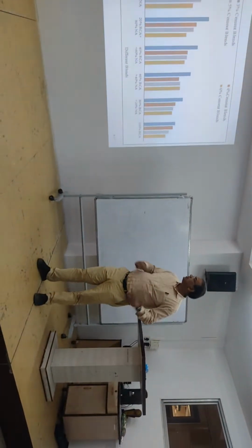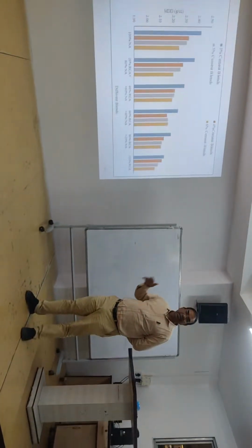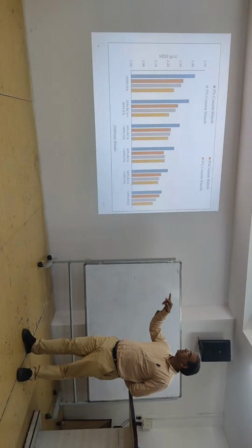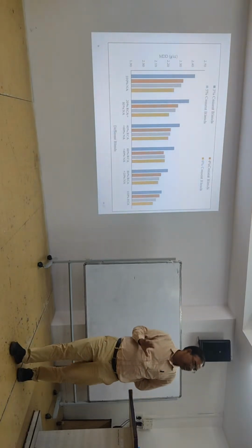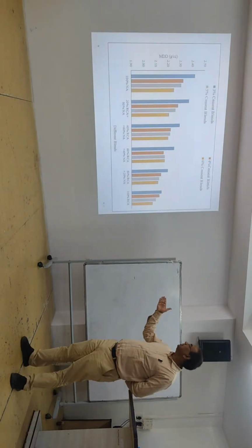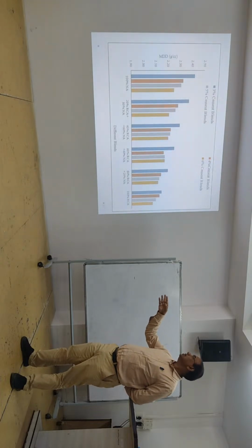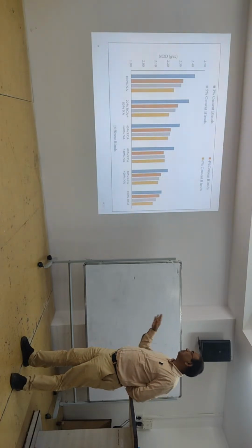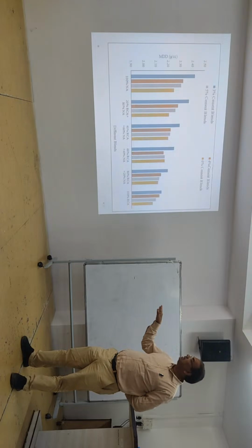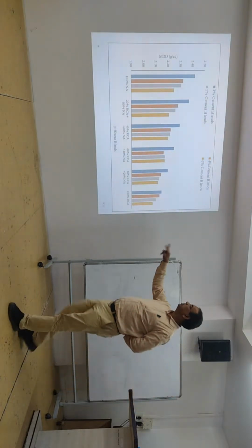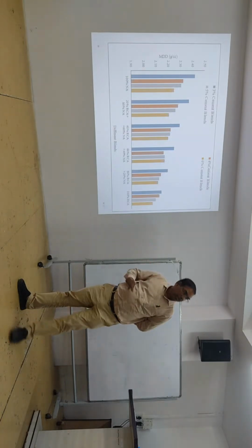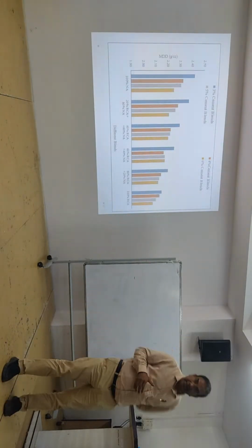We can see the strength of different blends and MDD. With 100% natural aggregate we certainly get good results, but even with 60% RCA we are getting an MDD of 2.1. We want 20% RCA and 80% natural aggregate, as the code gives direction.